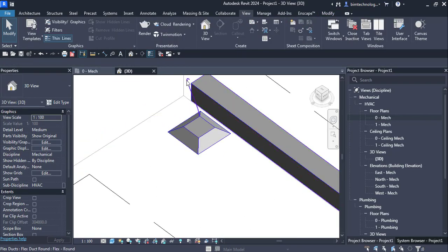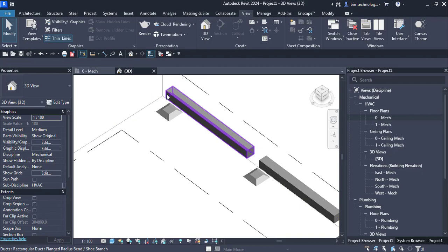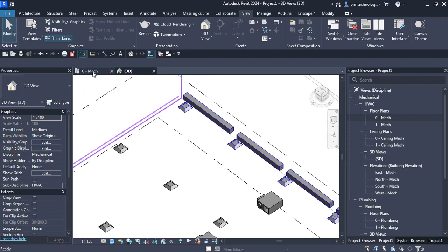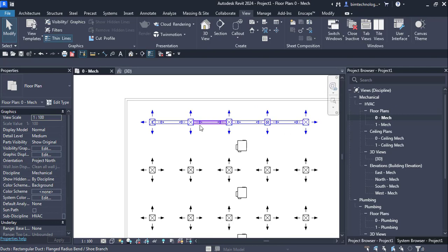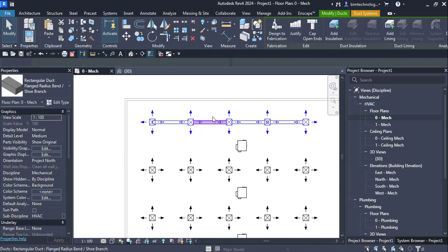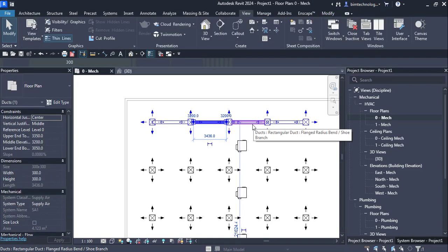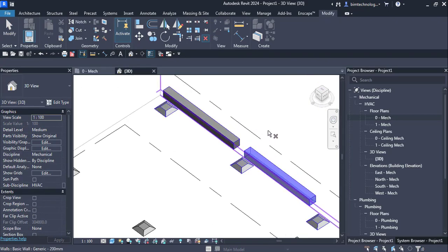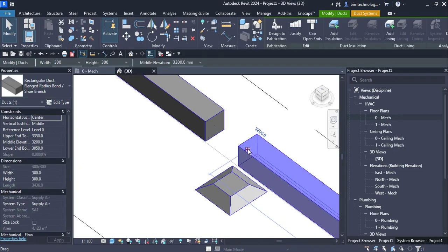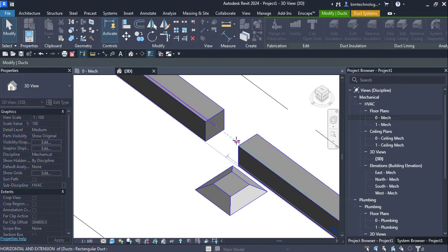And there is one connection, the solution is not provided. So what I can do is, here in the top view, we can see there are certain disconnects that have been done. So what we can do is, we can connect them in the 3D view itself. We can directly click on the control point over here, drag it perpendicularly and join them with the duct.